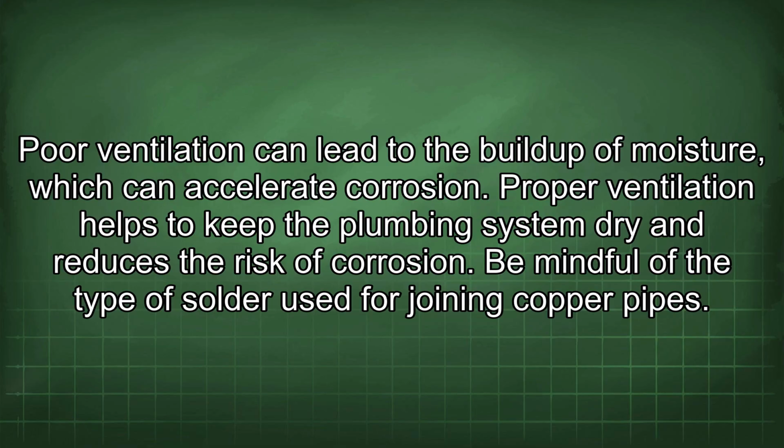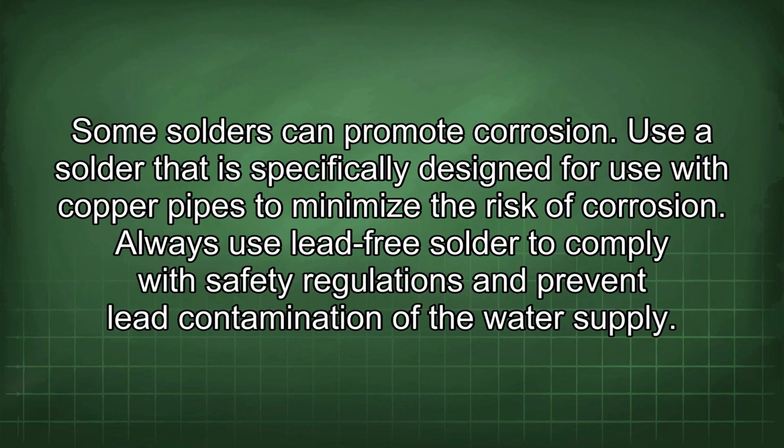Be mindful of the type of solder used for joining copper pipes. Some solders can promote corrosion. Use a solder that is specifically designed for use with copper pipes to minimize the risk of corrosion. Always use lead-free solder to comply with safety regulations and prevent lead contamination of the water supply.